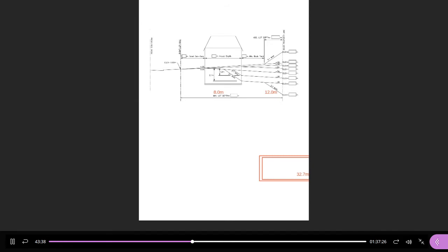Okay, so I'm going to come back to this. I need to discuss, remember the standard? What was the minimum slope? Usable space. What's the minimum slope? To what? I'm being picky now. To what? 2%. Very good. What's the maximum usable slope? 5%. Very good. Do you see 5% anywhere on my drawing? Do you see 2% and 3%? Positive, negative? Does anybody see 5%?